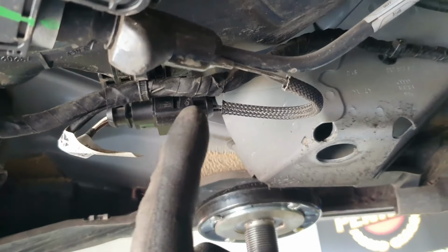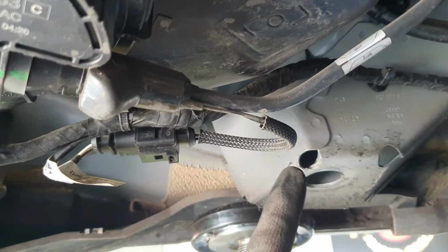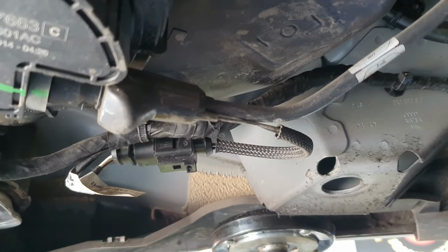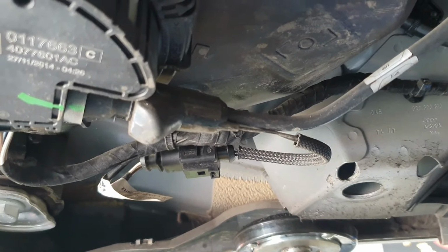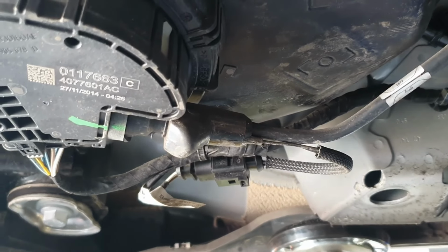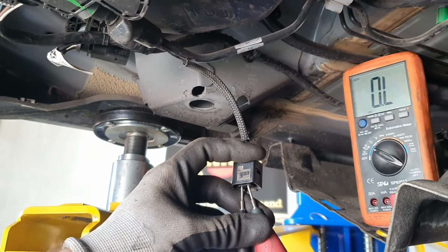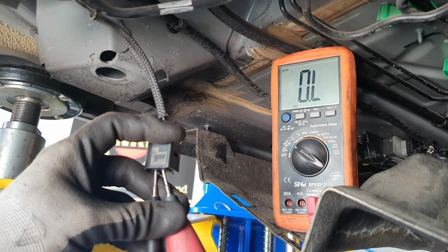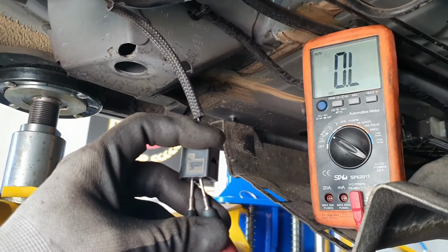So as per the TSB that we saw earlier, this is our heater, the two wires for our heater element. We're going to disconnect this, get the multimeter out, and check the resistance to see if we get a resistance or open circuit. That will tell us whether the heater element's failed or we need to look at wiring. I'll get that set up and get you back on. Alright guys, we're unplugged and testing the resistance of the heater element right now, and as you can see, we're open circuit. So no real need to go further with the wiring.